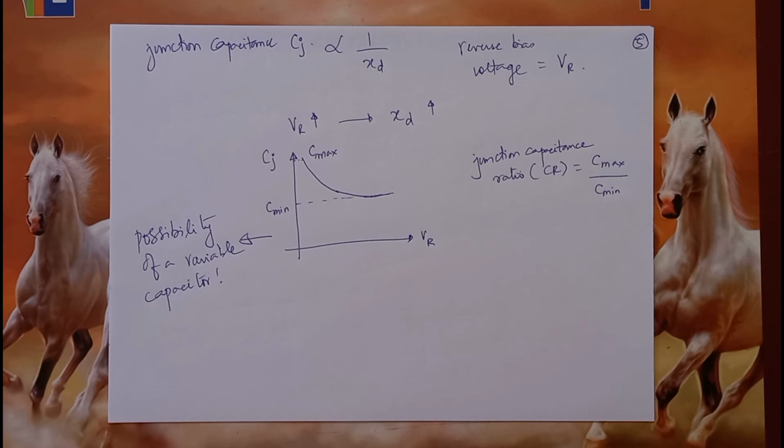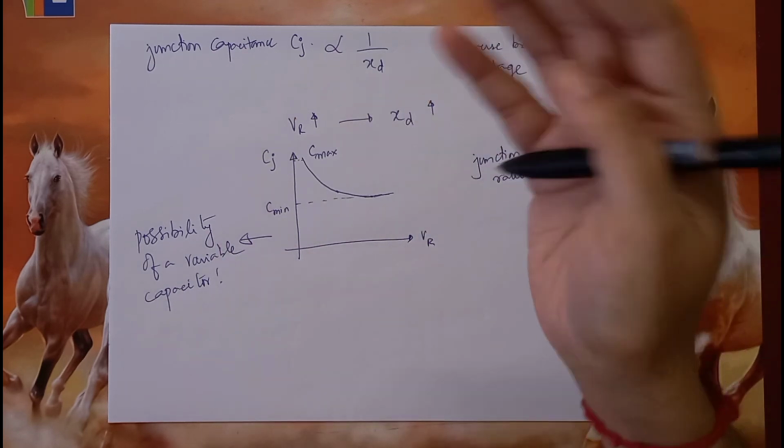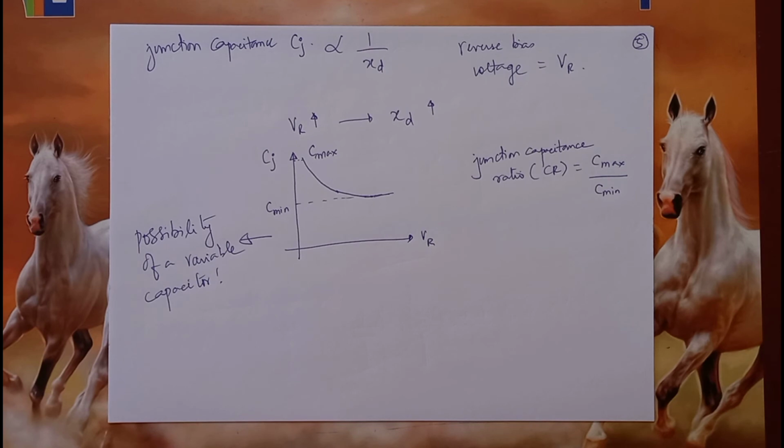So think how good that would be if we were to use them in impedance matching, if we were to use them in an L match network. Just by changing the capacitance value, I can change the frequency of matching. Or if I were to have resonance in an RLC network, I can change the capacitance value and change the resonance frequency. That gives me flexibility as a designer to use the diode as a variable capacitor and not limit the performance of the circuit.